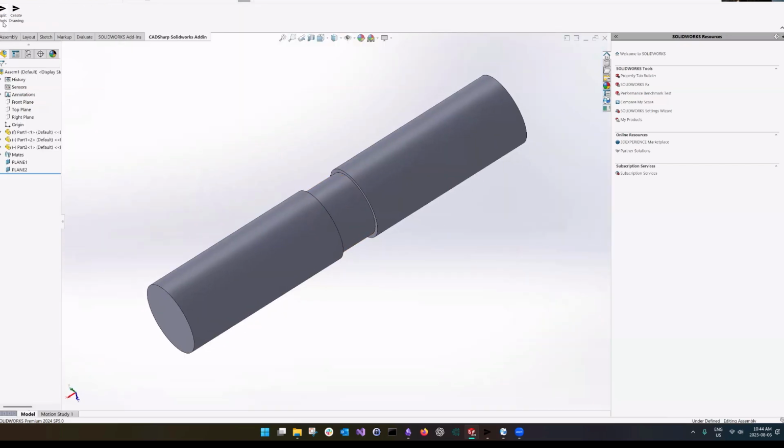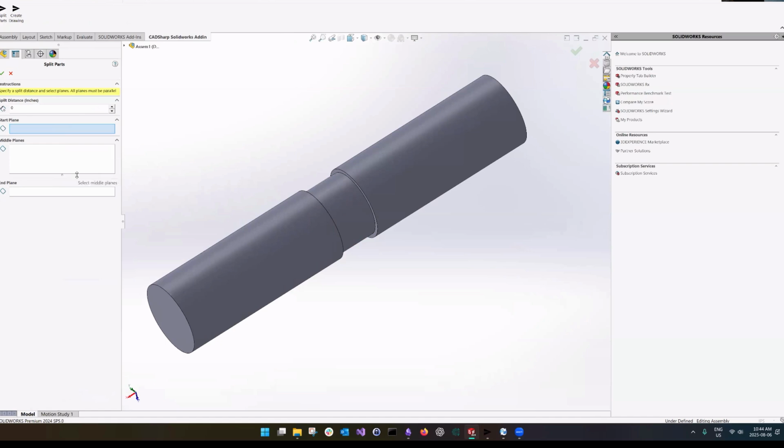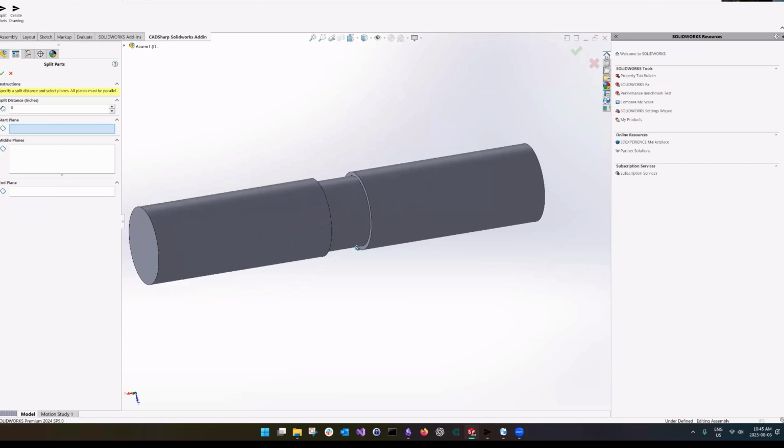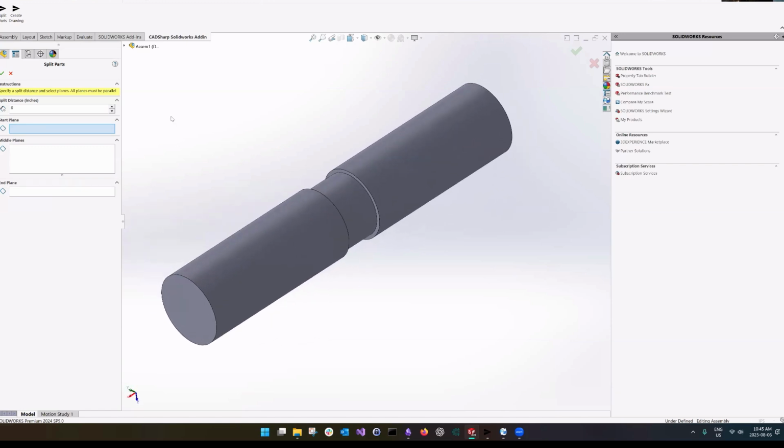Another more advanced one I've got here. So if I click this command here, we get what we call a property manager page. So this is a custom feature, but it's built to look like native SolidWorks. And we build these when we need a lot of model selections. So in this case, I'm applying a feature to an assembly that you can't do normally. So I'm going to split this, and this is made up of three parts. I've got two cylinders here of a large diameter. This part's duplicated. And then the middle one is just another cylinder with a smaller diameter. So I'd like to pattern cut that, which you can't do, well, in this manner anyways, by default.